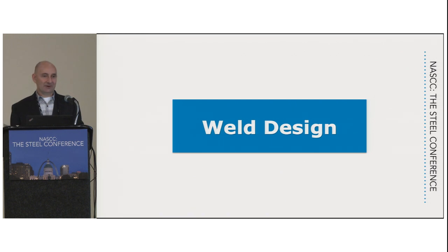And that's why I was saying earlier that it's really interesting. I tried to avoid this notional load method for years, hoping that I would get to retire before I had to learn it. But once I figured out that it was all based on things that made sense, once you dig into it, you see why everything is the way that it is. For example, you apply the load, that accounts for the out of plumbness of the column. So you can look and see where everything comes from, and it really makes sense.